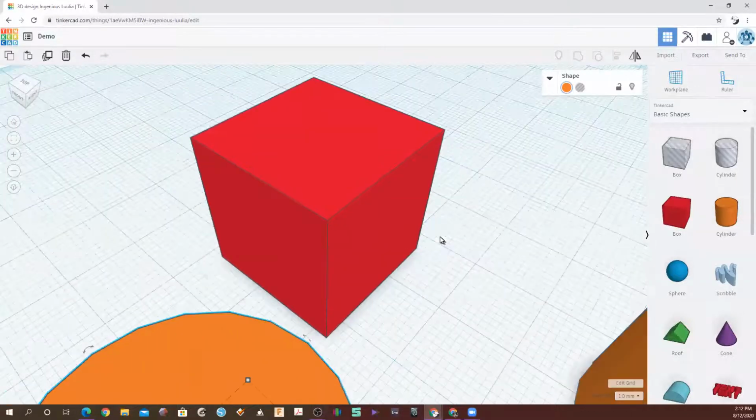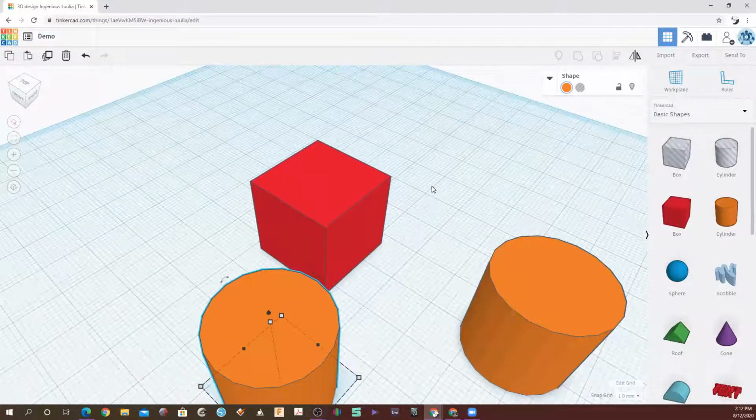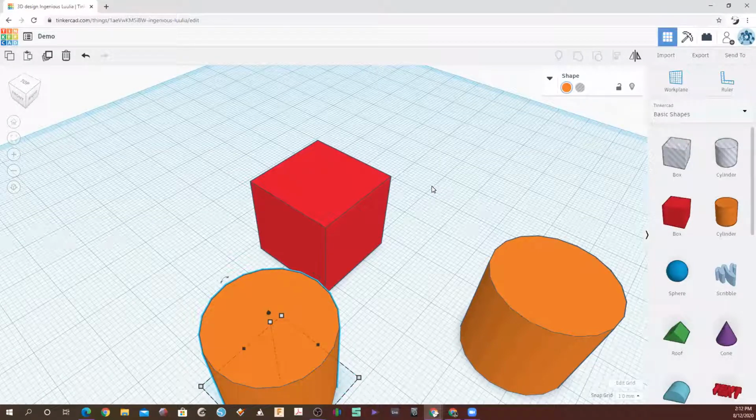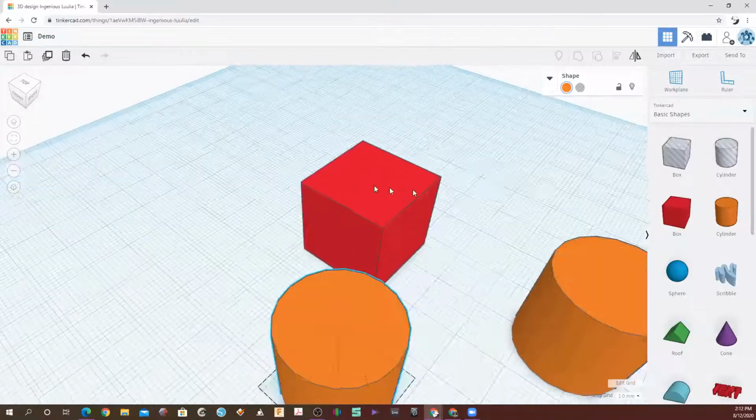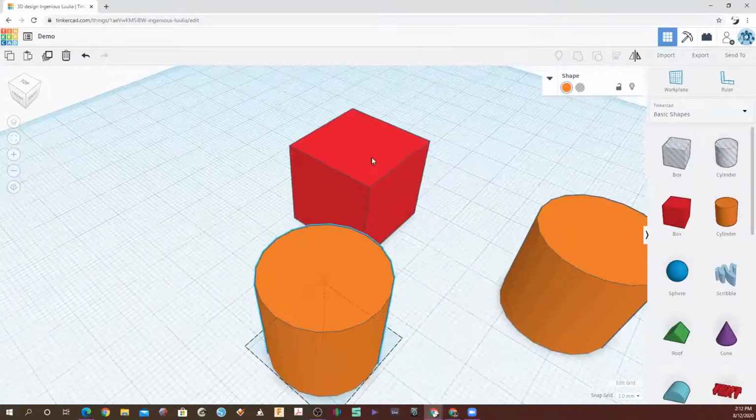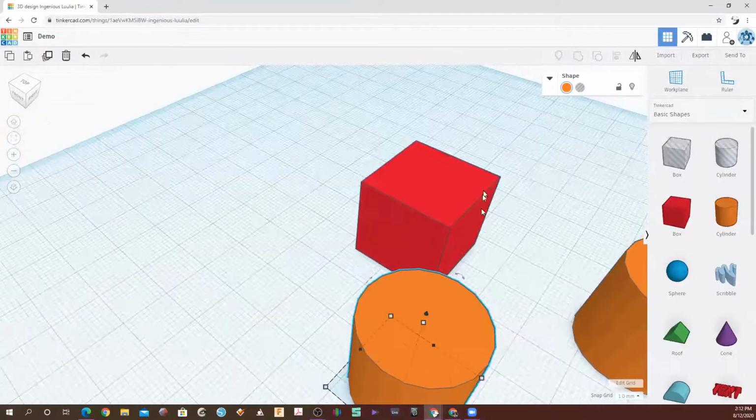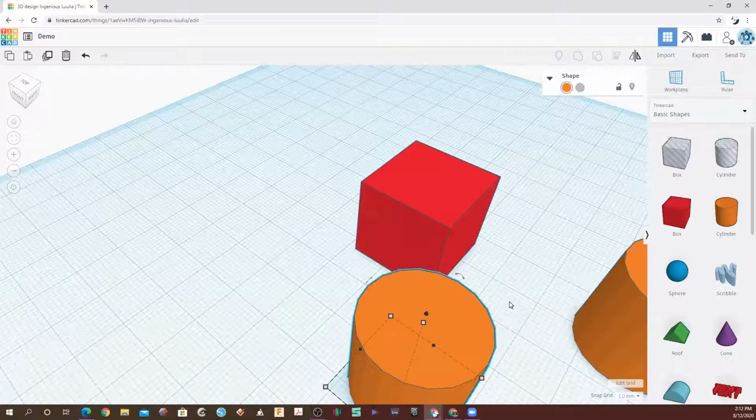Or there's one more, which is panning. So these are all kind of camera moves that we're doing. If you're familiar with any type of cinematography in real life with a real camera, these are different types of moves that you would do. The last one, panning, is literally moving the camera or your view left to right, and I'm holding the middle mouse button down. Instead of rolling the wheel, I'm pushing it down like a button.